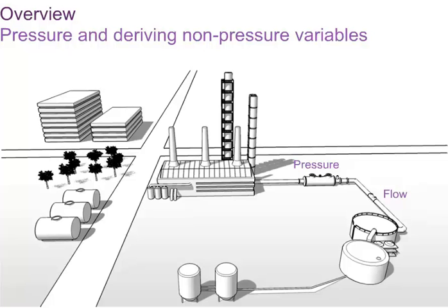These are flow rate in a pipe, level of fluid in a tank, density of fluid or interface level of two fluids in a tank. Flow rate is measured with a primary element and a differential pressure transmitter. For the fluid level in a tank, you also need a differential pressure transmitter if the tank is pressurized. If the tank has a connection to the atmosphere, this means it is not pressurized, you can use a gauge pressure transmitter. For density of fluid and interface level, a differential pressure transmitter is always necessary, very often combined with diaphragm seals.